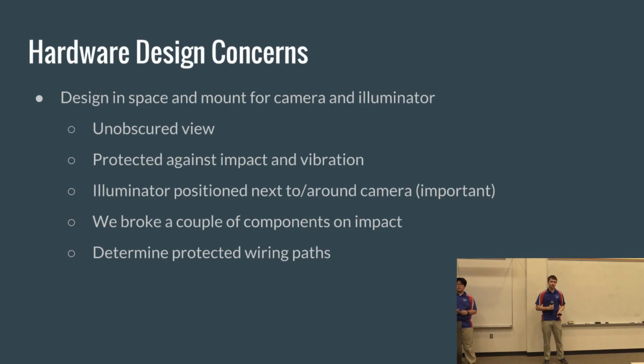We ended up losing one or two cameras to cables that were just mostly sawed through and were having spotty connection. So basically, when you're wiring up your cameras and stuff, make sure they go inside something if possible, so they're protected. Because if those get cut, you're going to be in trouble. They'll have weird issues, and you'll try debugging it for a while, only to find that it was actually a physical issue.